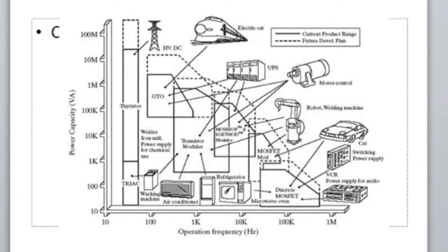It means that the torque acting on the belt drive is proportional to the difference of S1 and S2. R is constant, 9.81 is constant. What is variable? S1 minus S2 is the variable here. In the case of a belt drive, torque is proportional to S1 minus S2. But in the case of fan load, torque is proportional to the square of the speed, n square. T is proportional to n square. Therefore, when I increase the speed, torque will increase.